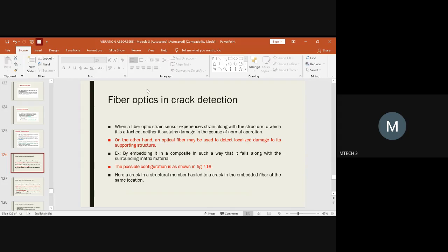So every microcapsule will have a self-healing agent. When you make a device entirely using self-healing material and shape memory polymers, you will have these microcapsules uniformly distributed in the body which you have synthesized. Suppose you have developed a material using self-healing material and suddenly, due to some accident, a crack comes into the picture.